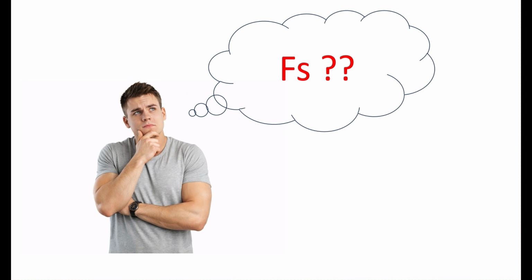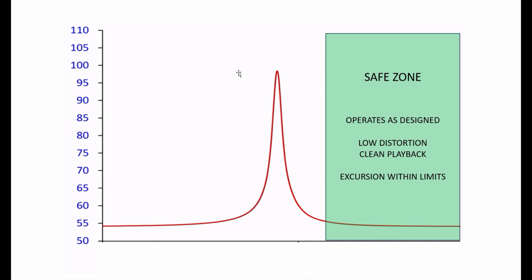So this brings us back to the question of, can I play my speakers below the FS? Well, it's a little bit like the Xmax Xmech situation that we spoke about earlier. So, before we said, this side of the FS, the speaker is dominated by the cone inertia. This side of the FS, the speaker control is dominated by the spring forces, and the speaker driver is not so good at controlling the cone by controlling the spring forces, right?